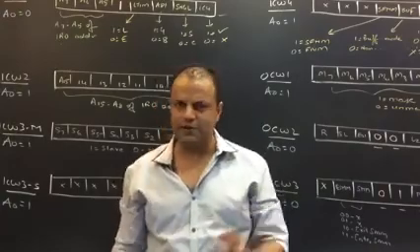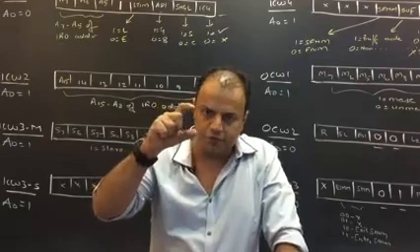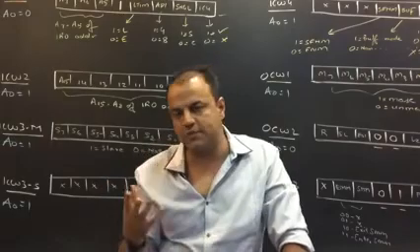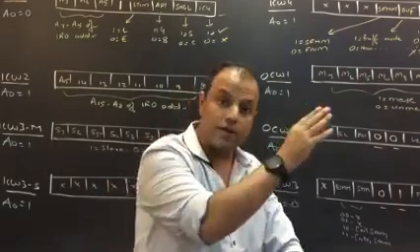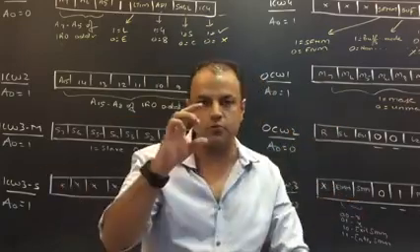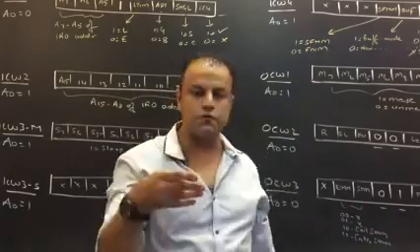4 is sufficient because I told you, long time back in the interrupts video. You can never decide the size of an ISR. An ISR can be as small as possible, as big as possible. At those locations, ISRs are not stored. At those locations, a call to the actual ISR is stored, and from the ISR you return to the main program. So what you need to store is a call and a return. Call is a 3-byte instruction, return is a 1-byte instruction, so 4 bytes are enough.